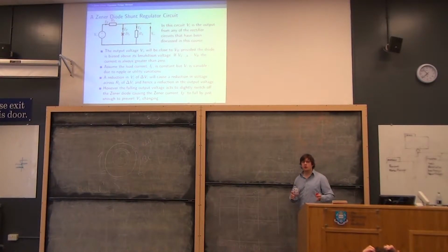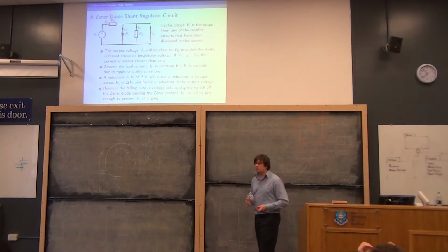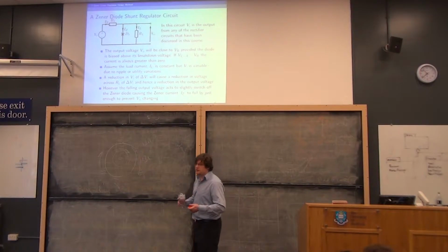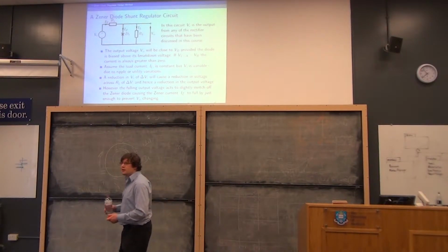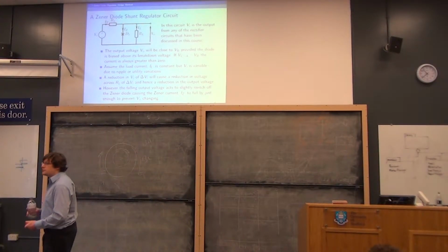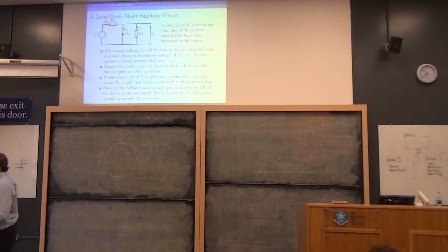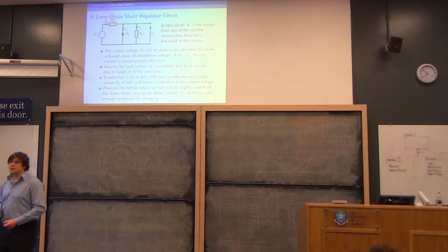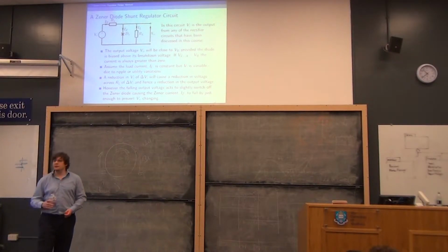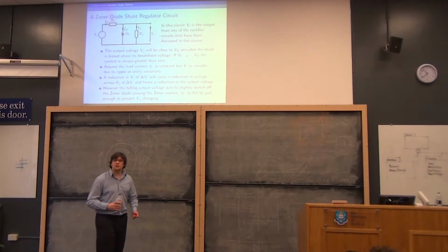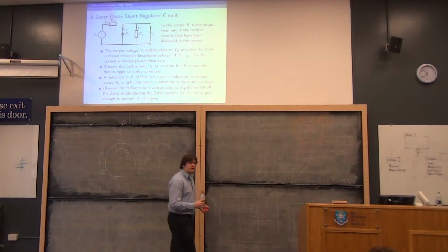Now just about right could be quite wide. Standard examples could be, depends a lot on your application, but anything from RS is a kilo ohm to RS is 3 or 4 ohms. RL will be in the region of 10 kilo ohms, maybe up to 100 kilo ohms. So in all circumstances, almost, RL will be much bigger than RS.